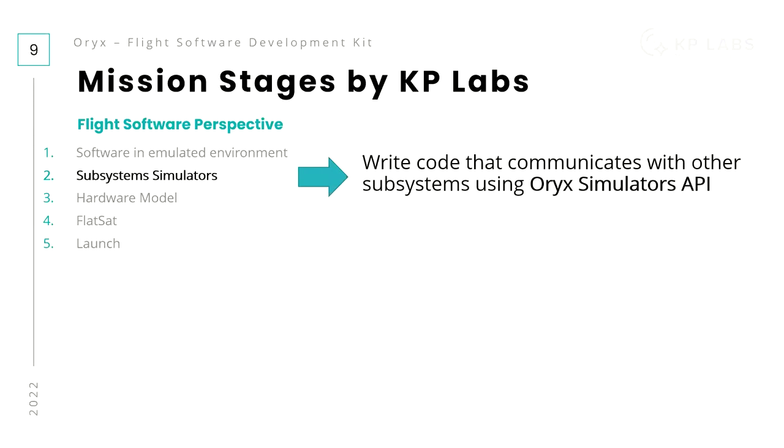So the power supply from Intuition One, again as an example, uses I2C as its control bus. So we will create something that has the same operations as you can do through I2C. Of course, it doesn't control anything. It just changes the flags in the memory, but we can then verify if it works correctly, right? We can set the simulator in a state we want and see if our code reacts.